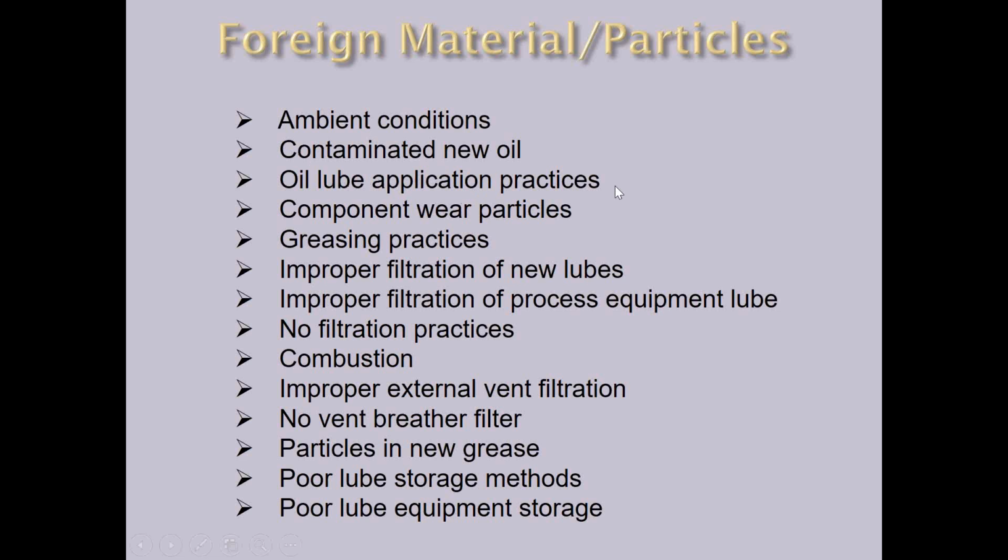Our oil lube application practices. What are we using to put the lubes in our equipment? I've got pictures of Downy bottles and Tide jugs and Drano bottles that people are using to add oil. How well were those cleaned? Water bottles are another common one I see. You have to get good, clean equipment to put your lube in. Then we get particles from the components that are wearing. As we wear out our equipment, there are particles in the lubes from our equipment.